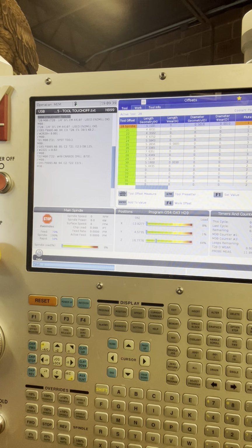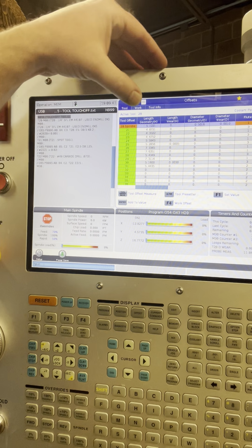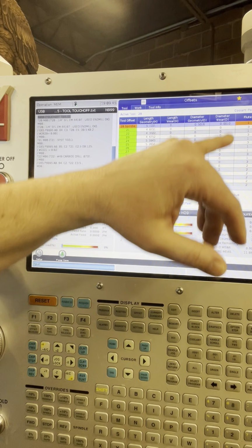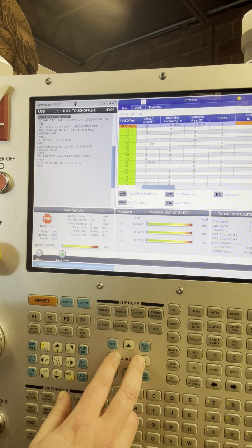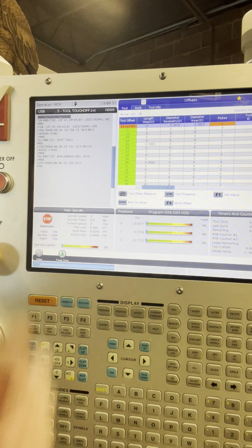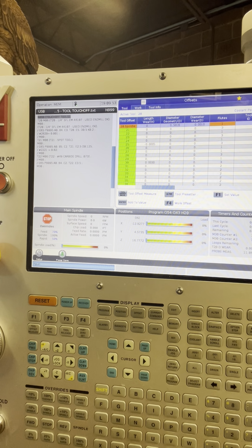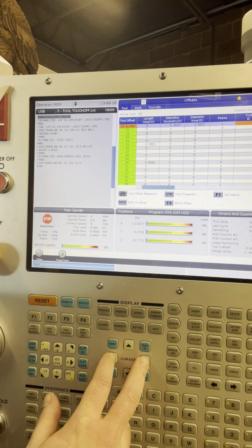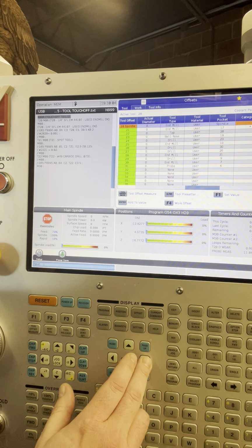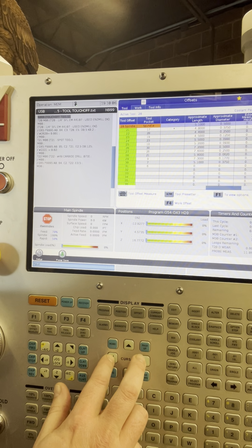So every time you touch off a tool, every time it gets this number here, it's writing that number in there. Not the flutes. Do you have, no, yours doesn't even have it, right? No. There's another column for the programmable coolant nozzle, and it's just 0 to 20. I'm guessing the coolant position is on the top too. Yeah, it does say 20. So maybe you do have it. No, I don't see it.